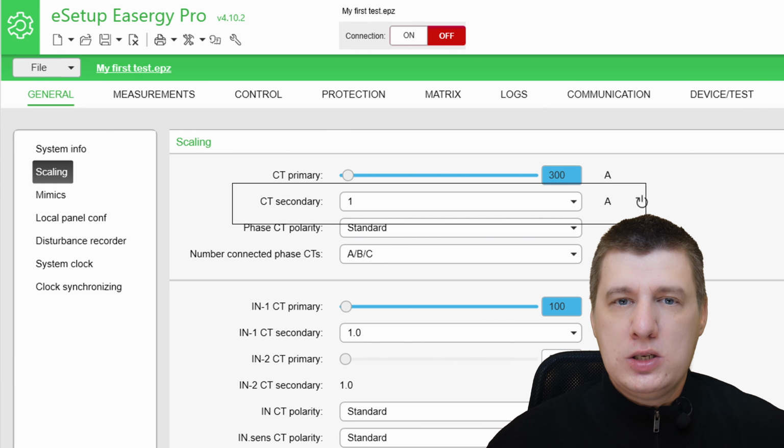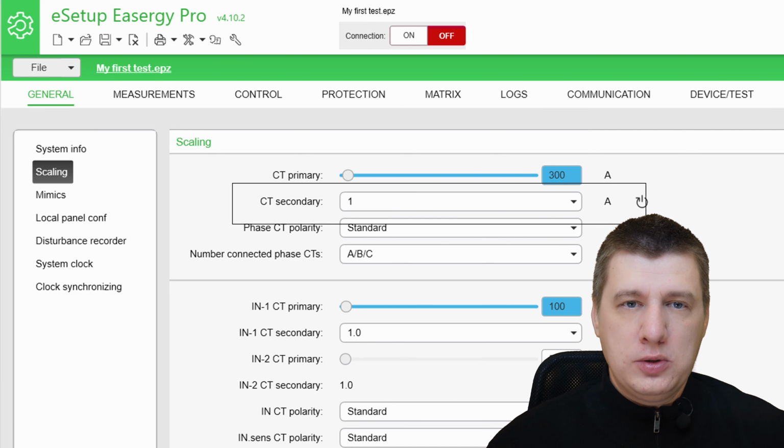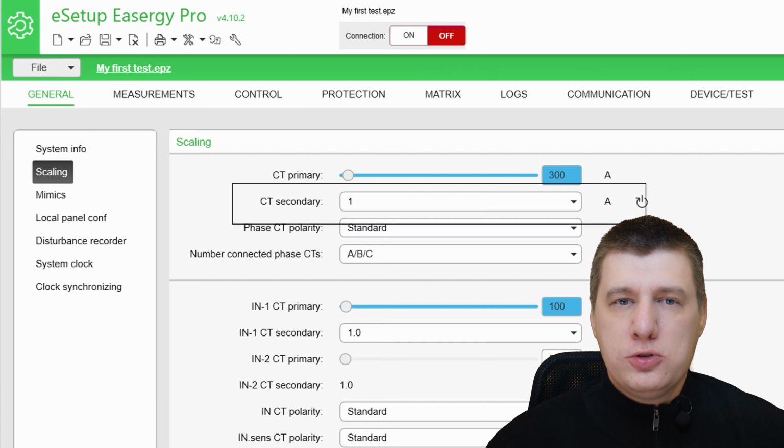Terminals and secondary wires, conventionally marked S1 and S2, are connected to the relay slot A analog module. For modules using low power sensors, the secondary connection is made via standardized RJ45 connectors rather than screw terminals. It is recommended to use sheathed cable shielded by tinned copper braid for core balance CTs.